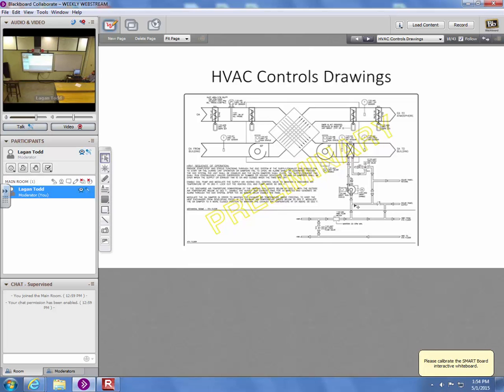In the commercial world, you have the option. You can say, I want factory controls, or no, we hire a controls contractor who's going to do controls throughout the whole building, custom. And if it's a custom controls package like that, they should be creating schematics that show, in a schematic sense, the HVAC equipment. Like in this case, this is an HRV, heat recovery ventilator. And then they'll show the locations of all their different controls devices.